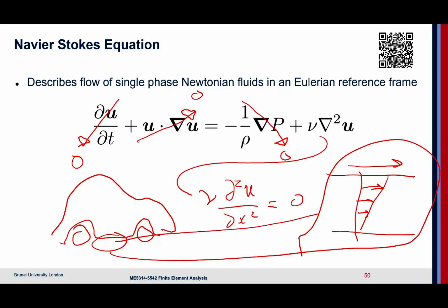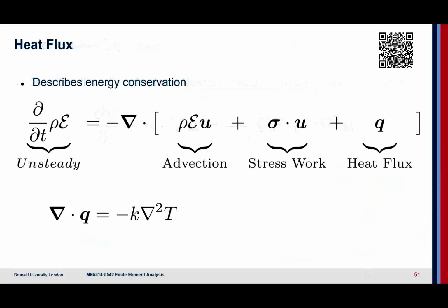So let's say you were doing some sort of large-scale analysis. Actually, it might be simple enough to use a one-dimensional model, just to look at the drag underneath the car, for example. Or if you're modelling, say, a bearing, the actual gap in the bearing, potentially you could model using this Couette flow. And lots of people simulate many cases using this model.